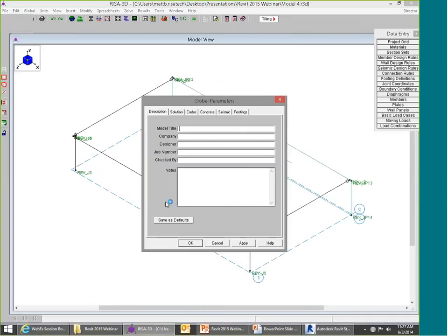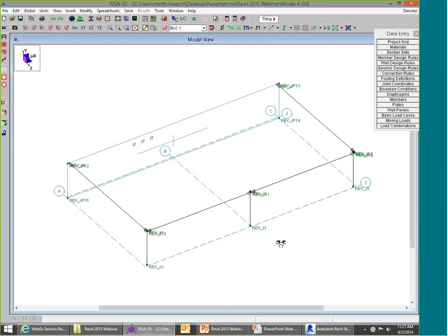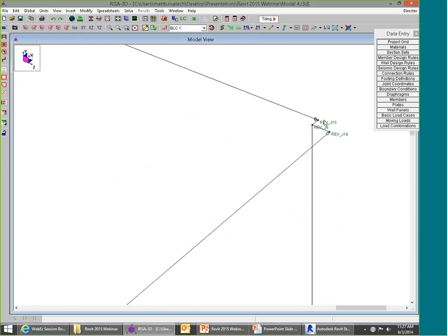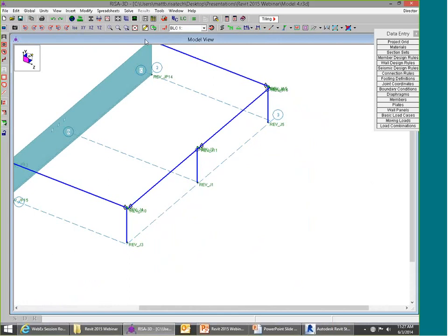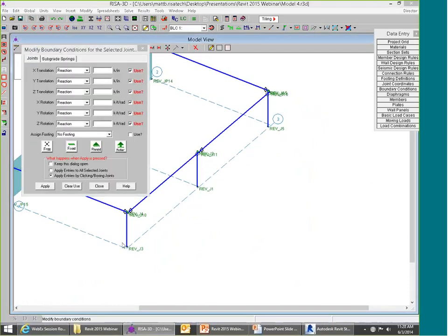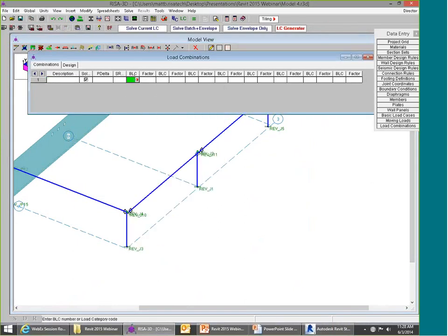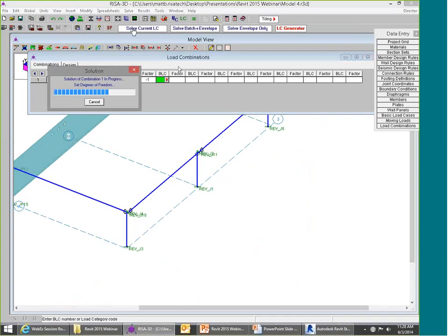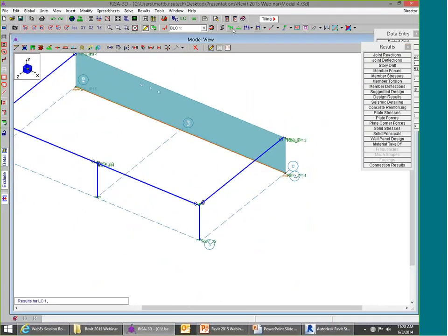And with that update, we can take a look at the RISA 3D model, and we're going to see now that these columns are, in fact, connected using these rigid links on here. So that correctly worked. And at this point, I should be able to solve this model without getting instabilities. So I'm going to come into this model here, and I'm going to put some boundary conditions in. And I'm going to solve this model just for gravity only. We finish the solution, no instability warning, so everything worked out all right.